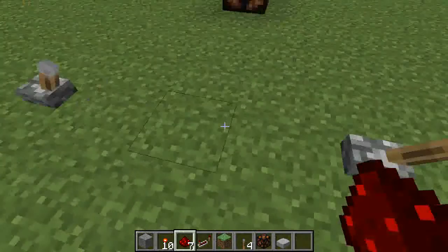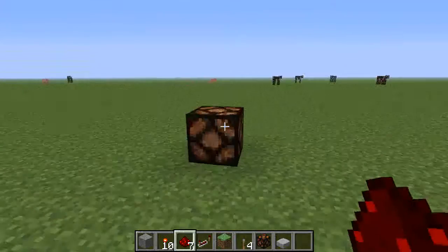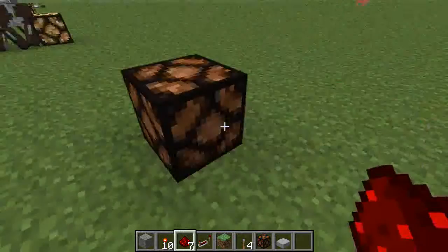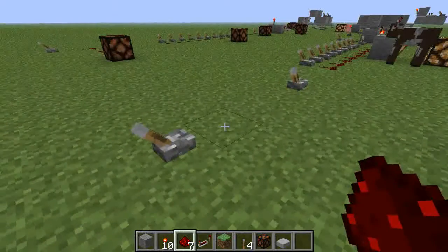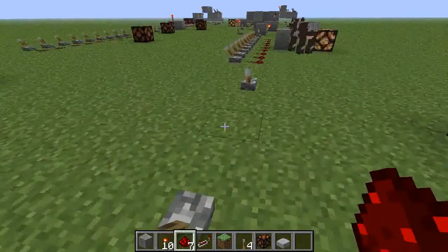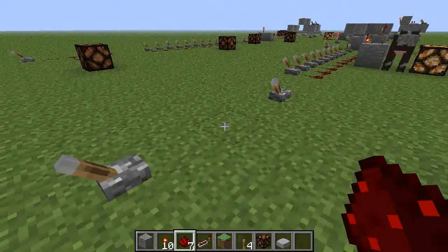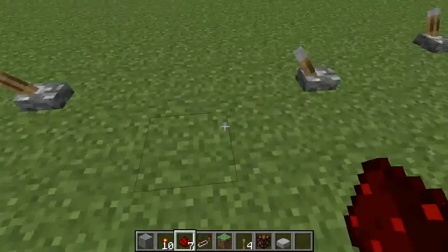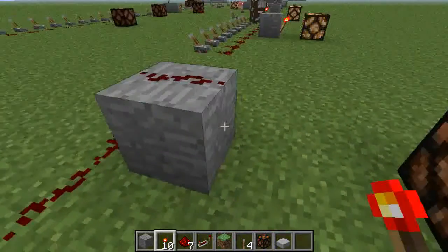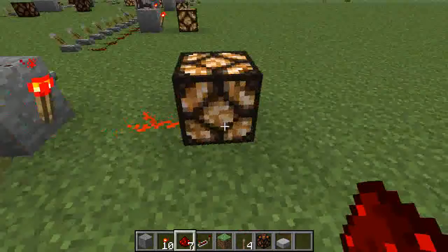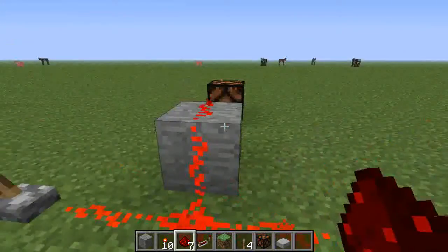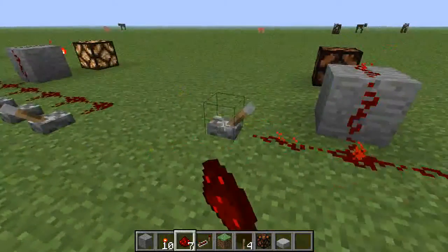Okay guys, so here we have our two inputs and our output. And we want to make it so that in this position when they're both off, this is on, but at no other times is it. But as we said before, it's the inverse of an OR gate. Hence, NOR gate, not OR. So, why don't we make our OR gate, and then negate the signal. Jeez, I always say symbol. Alright, and see? Works just like we expected it to.